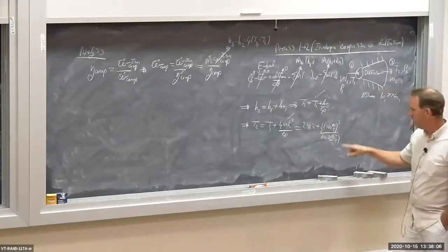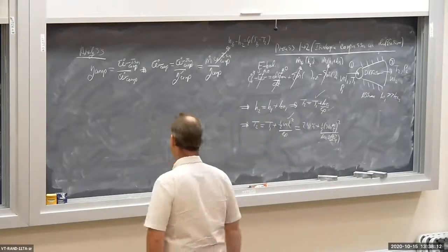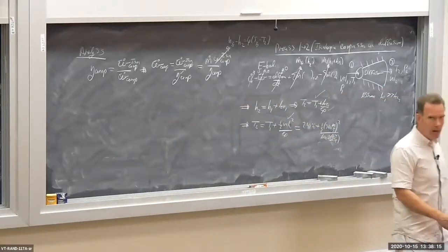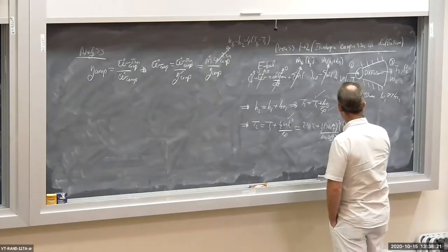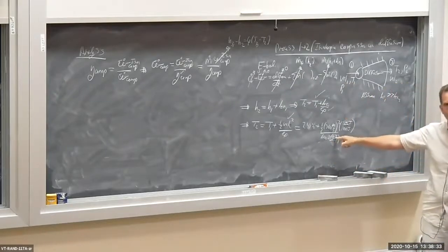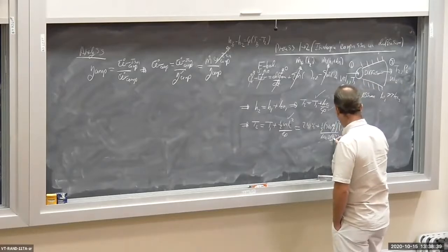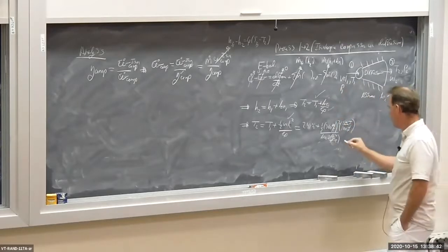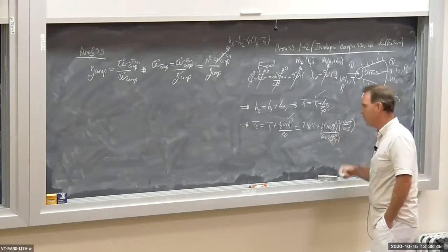One little thing here: the kinetic energy term will have units of meters squared per second squared, which is a joule per kilogram, not a kilojoule. So I have to convert from joules to kilojoules, since there are 1,000 joules per kilojoule, so the unit matches my Cp. The joules cancel with the kilogram, the kilojoules cancel, and I'll have 1 over Kelvin, so the unit on this term is Kelvin.